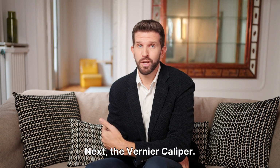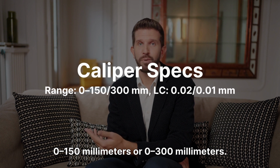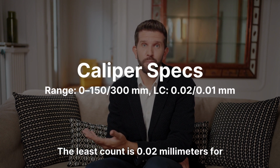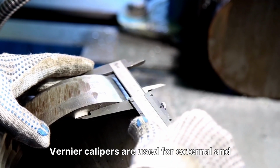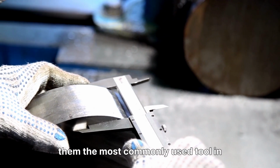Next, the vernier caliper. It typically has a measurement range of 0 to 150 millimeters or 0 to 300 millimeters. The least count is 0.02 millimeters for metric versions and 0.01 millimeter for digital versions. Vernier calipers are used for external and internal diameter, step, and depth measurements, making them the most commonly used tool